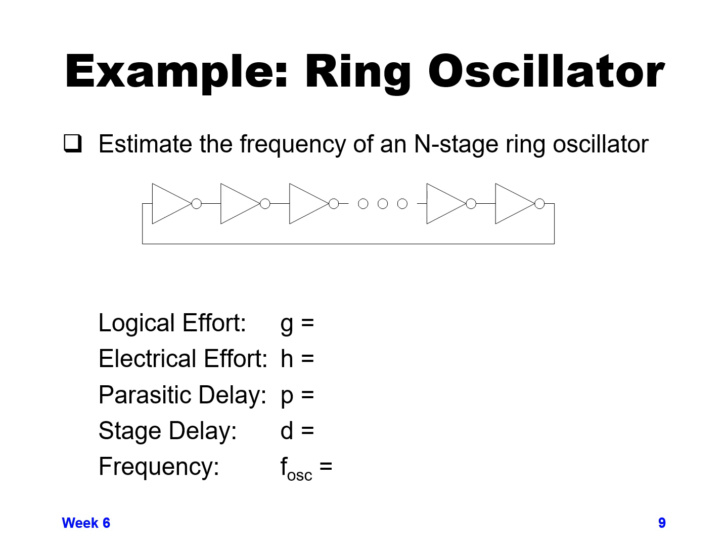Now let's go through another example. In this case, relatively simple, but instead of just computing the logical effort, we'll be trying to compute overall delay. And it'll be simple because it's all the same type of gate. So our example here is a ring oscillator.